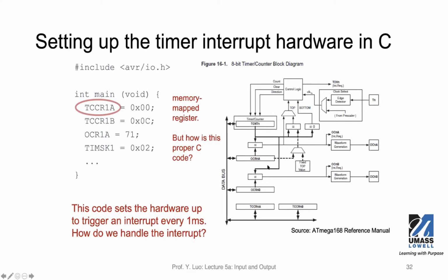It has a few registers that you can see, TCCRnA, TCCRnB, where n refers to the number of the timer controller. The microprocessor or microcontroller may have multiple timers. So for this example, you find TCCR1A, and if you use a different timer, that would be TCCR2A. Likewise, OCR1B or OCR2B, etc.